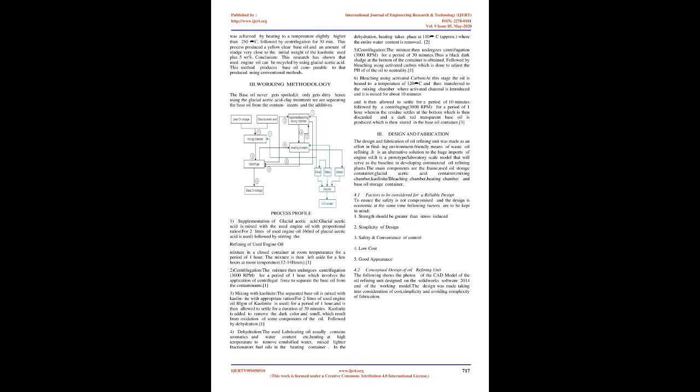Neutralization. The bleached oil was neutralized to adjust the pH of the oil to neutrality. At this step, 4 wt% of the oil of hydrated lime was introduced into the bleached oil, taking into consideration the pH of the bleached oil at a given point in time. The bleached oil was neutralized with continuous manual stirring for 10 minutes.